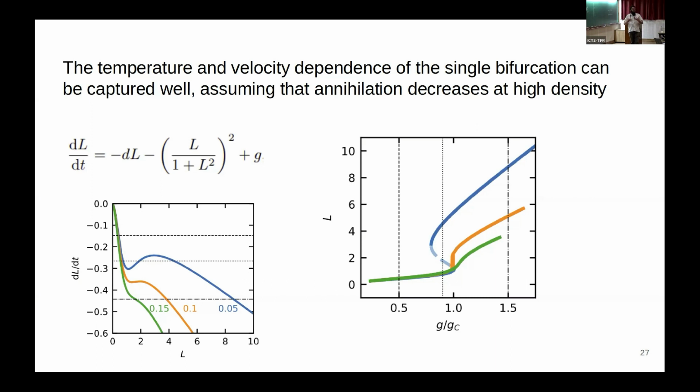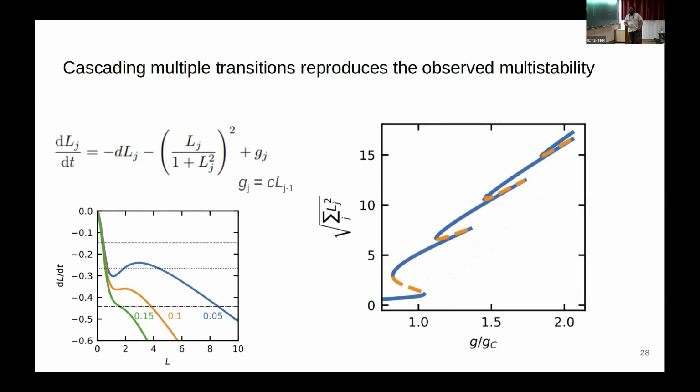Already drive at scales which is half the system size. So we don't get much further modes excited. But when we drive at much smaller scale, when the ratio between system size, between the large scales and the forcing scales, is much larger, then there are more Fourier modes which can participate non-trivially in the flow, which makes it necessary to model more of these modes with the same dynamics, more or less. That's what I would say. Oh, okay.